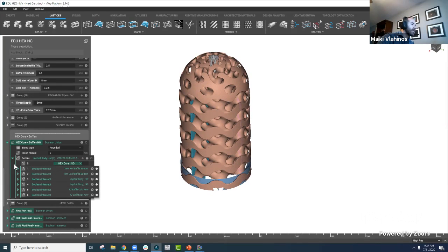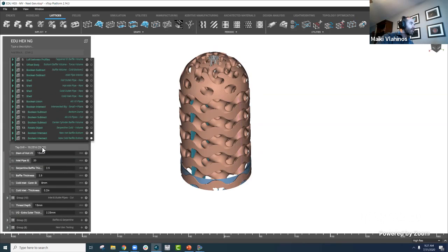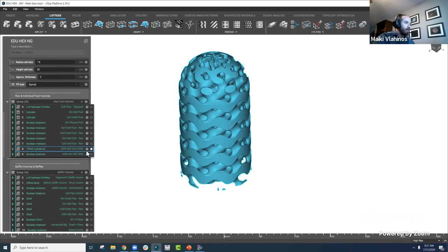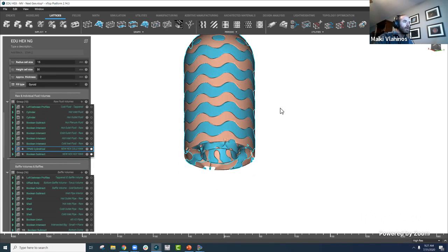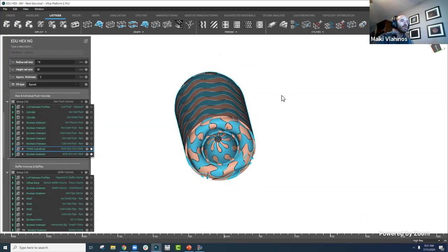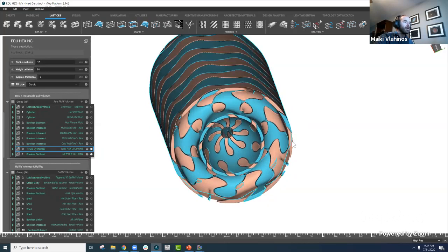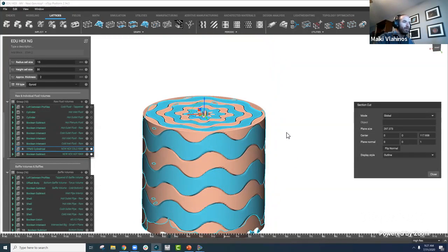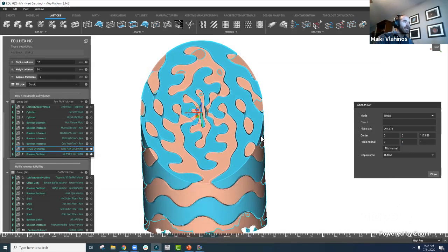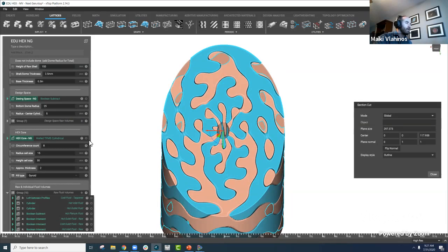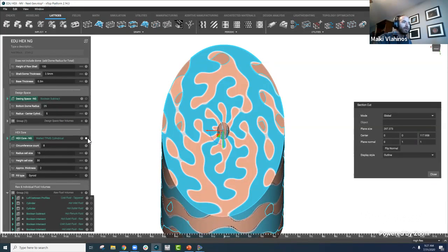And yes, again, it is 2 fluids that we have here, and that's one of the beautiful things about these structures, is that they yield themselves to separating 2 regions in space, so that you can make ideal heat exchangers out of them. So this is just those fluid volumes, and if we do a cross section, you can kind of see internally how there's that gap between the two, and that's just what the heat exchanger core is. So it kind of fills in that gap, and that's obviously where your heat is going to transfer through.